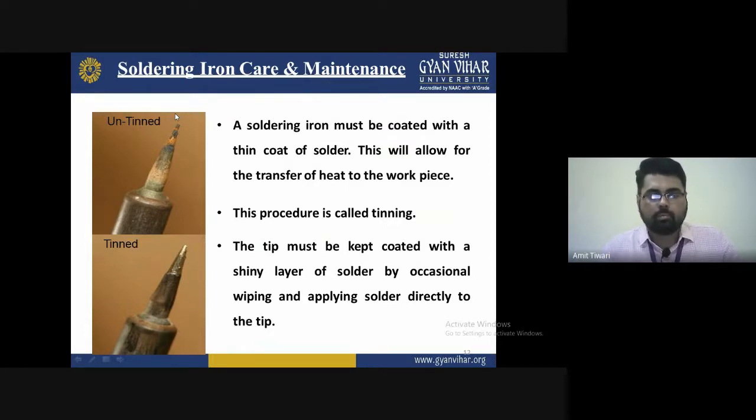These are some of the instruments we use for the basic role during soldering. Because if we are not maintaining the temperature of the iron tip, then it is not possible to transfer the heat to the surface of the joint, and during this time a weak weld occurs. If you want a stronger joint, you just need to maintain the temperature of the iron tip. It is the most important requirement.